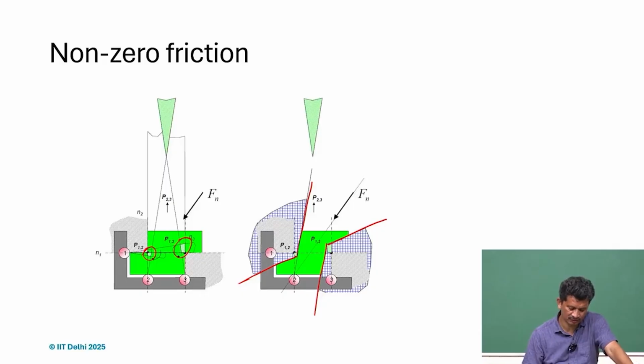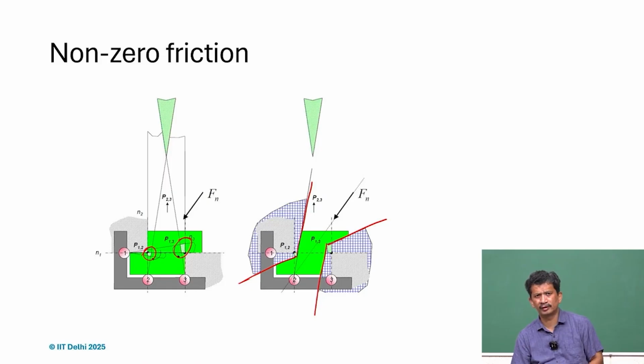Ultimately what we see is it has enlarged, and no wonder if we find no solution for certain cases. So, it means then we have to work out, and maybe we have to do the repositioning of the pins. The idea behind showing all these examples is that friction really complicates the design, and sometimes we may not have a solution. So, things can get jammed or locked, and therefore we have to be aware of those issues, and if not, then try to find ways to minimize the effect.